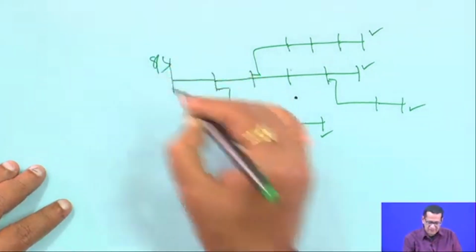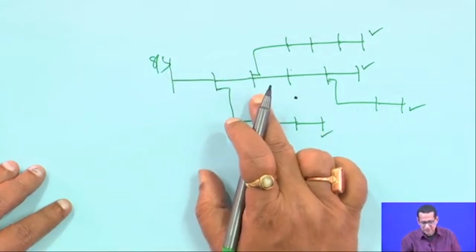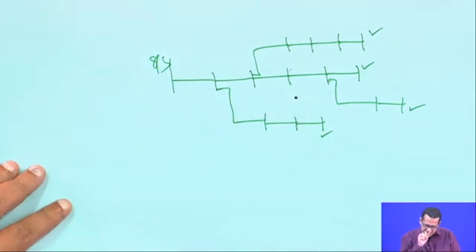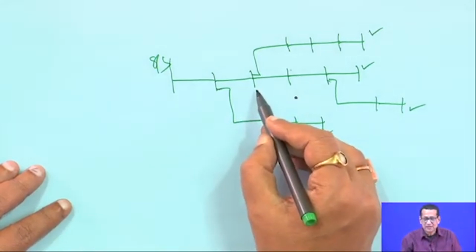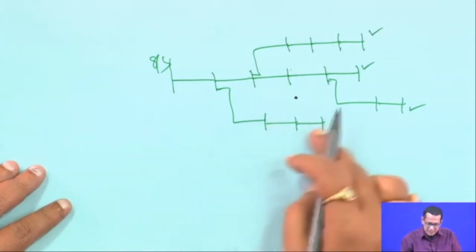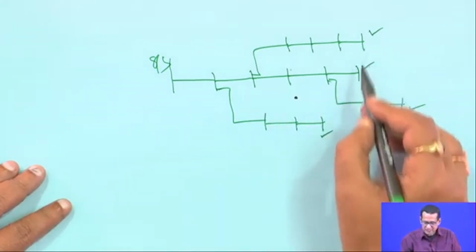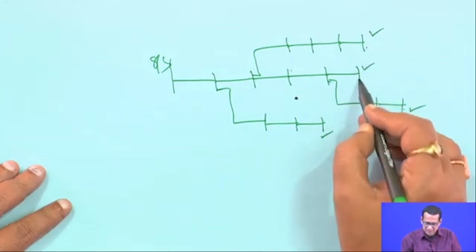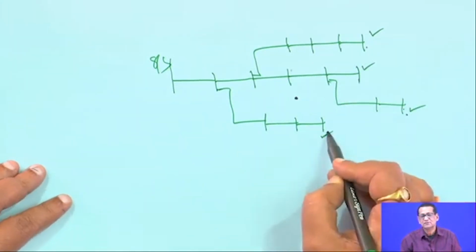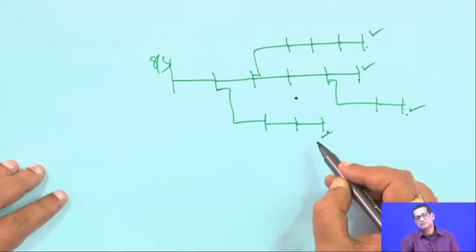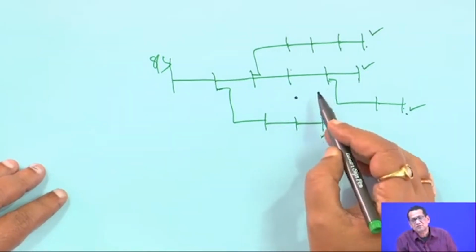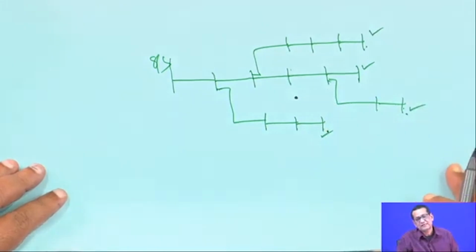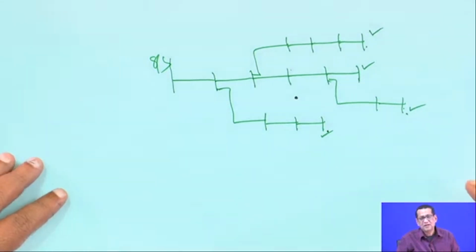This is of course the substation. So, you have to find out each node's SI value and increase the load at every node. You may find that the last node may not be sensitive to voltage collapse, and it may become some other node, depending on the load characteristic, the R and X values, and your load values, how they are.